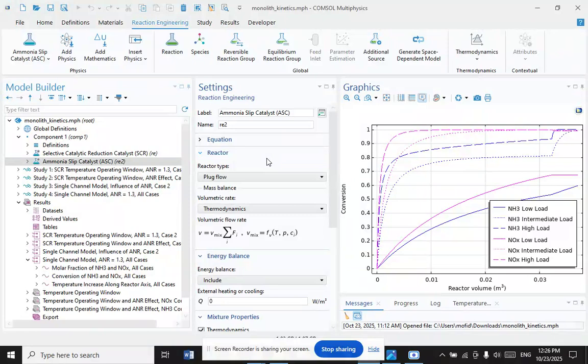Others are designed to burn off the accumulated particulate either passively through the use of a catalyst or by active means such as a fuel burner which heats the filter to soot combustion temperatures. This is accomplished by engine programming to run when the filter is full in a manner that elevates exhaust temperature in conjunction with an external fuel injector in the exhaust stream that injects fuel to react with a catalyst element to burn off accumulated soot in the DPF filter or through other methods.